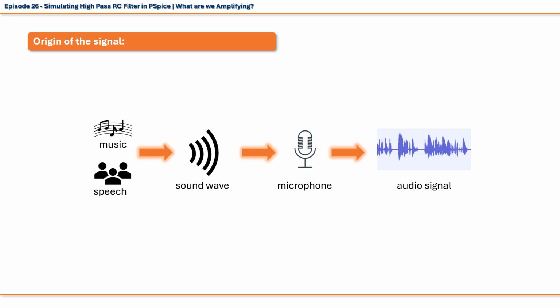There are several ways that a microphone converts sound into an electrical signal, but what is common for all types of microphones is that it always contains some sort of membrane that oscillates under the pressure of sound waves, and then that oscillation gets converted into an electrical signal. Do not mix sound with audio signal. The first one is a mechanical pressure wave that travels through the air, and causes it to oscillate. Audio signal is the electrical representation of that pressure wave, generated by the microphone. Simply put, a microphone converts sound, that is the mechanical wave, into a corresponding electrical signal.